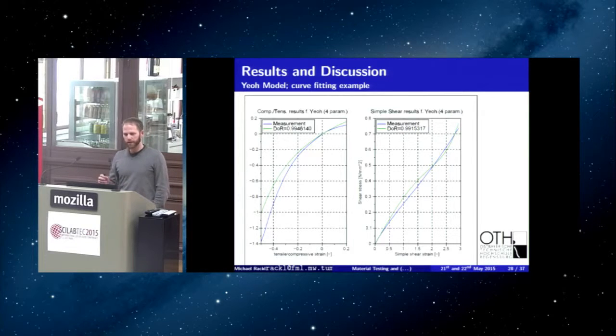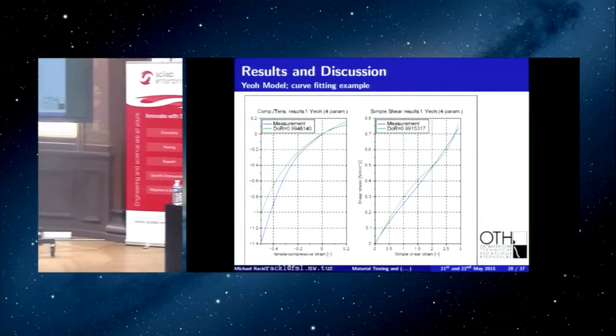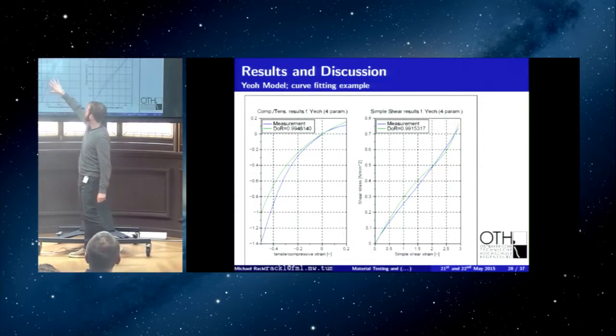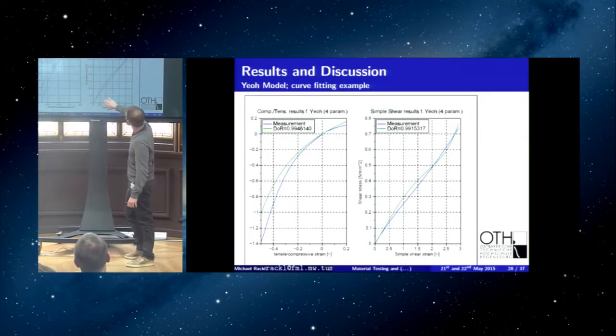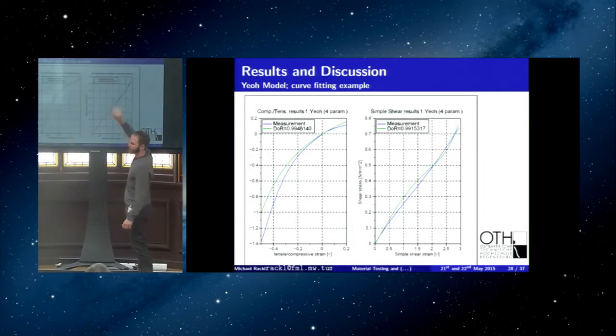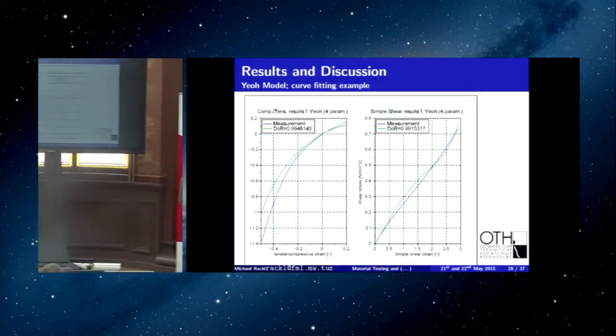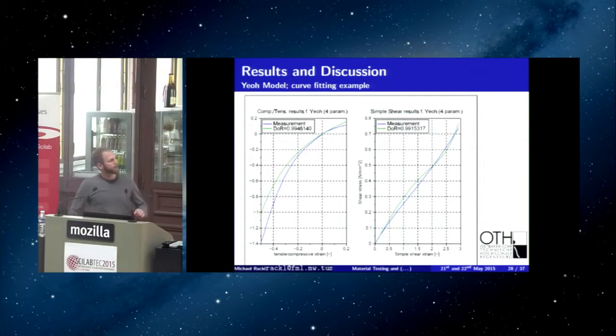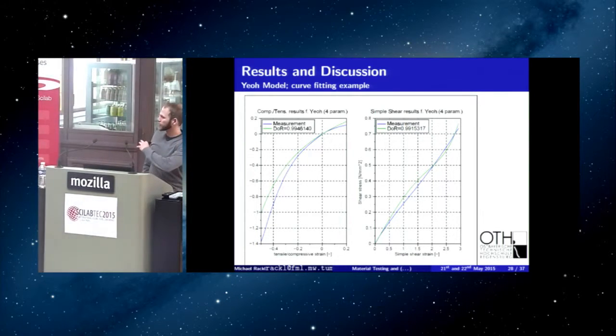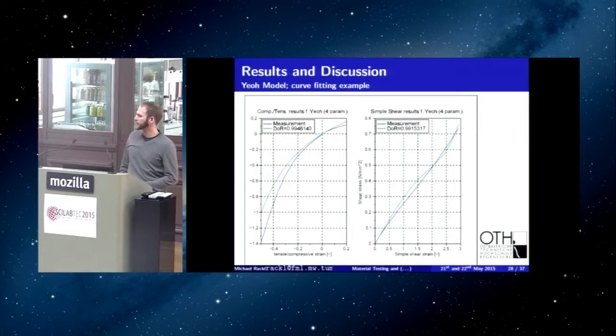However, the Yeoh model tended to show results, as you can see here. I guess this is somewhat okay, even though it's not perfect, but the course of the curve here, going like this, is not exactly what someone wants to see, because it might be really close to the measurement data, but the course is not really predictable because it changes direction a couple of times.